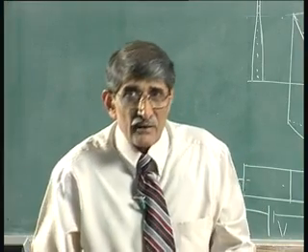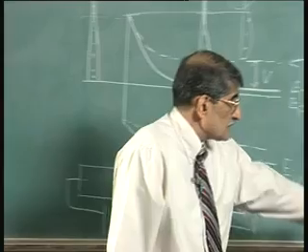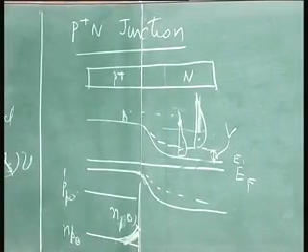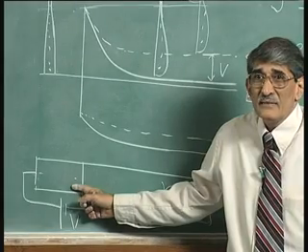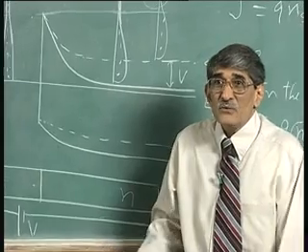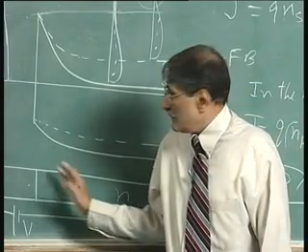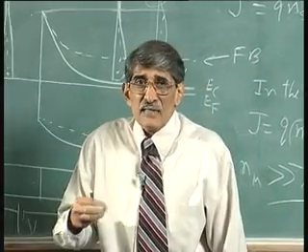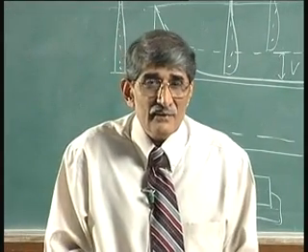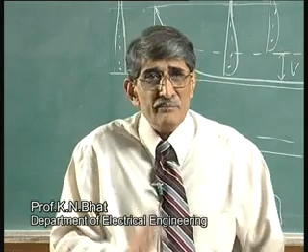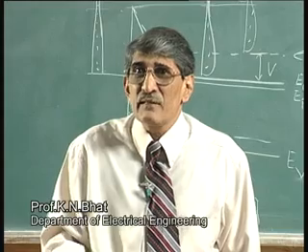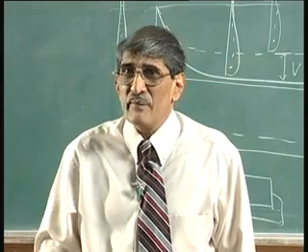Also, I have pointed out to you today that the charge storage here is there because minority carriers are stored. What about charge storage here? Absolutely no charge is stored, because whatever is injected is very small. No charge storage effect here, either here or here. Whenever the charge storage effect is absent, you can say the device is faster. So, in high speed circuits, it becomes very effective to use a device which has no charge storage, that is the Schottky barrier diode.